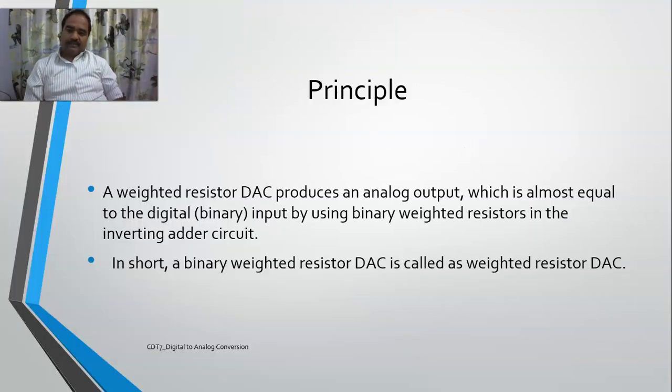This weighted resistor DAC produces an analog output by taking in the digital binary inputs using binary weighted resistors. It is an inverting adder circuit, and I'll show you the diagram and we will determine the output voltage equivalent to the binary digital inputs.